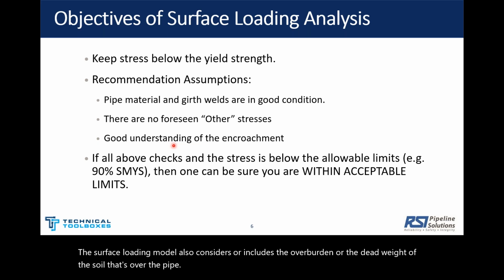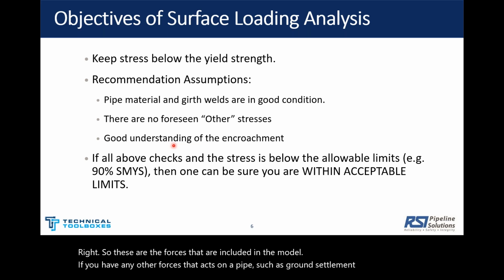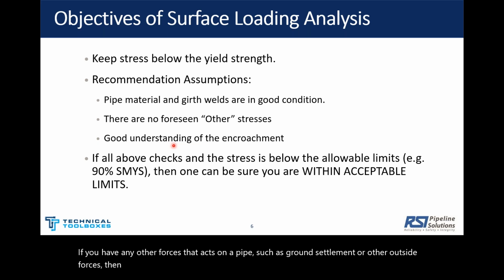So these are the forces included in the model. If you have any other forces that act on a pipe, such as ground settlement or other outside forces, the CEPA calculator does not include them, so it's up to the engineer doing the analysis to account for them.